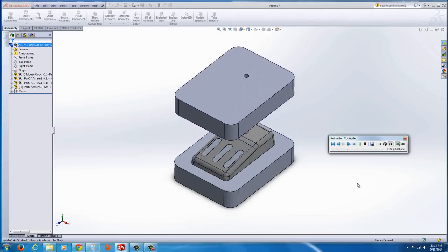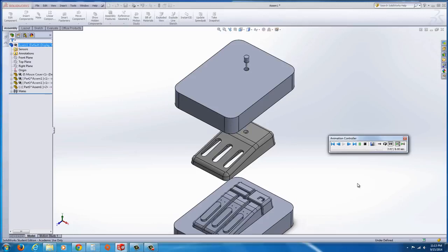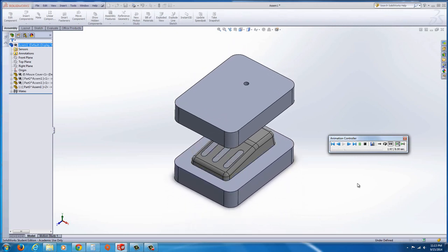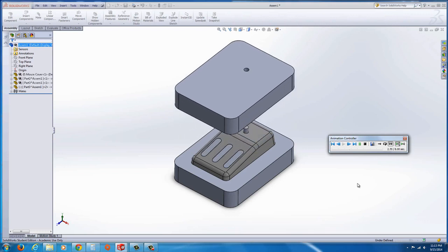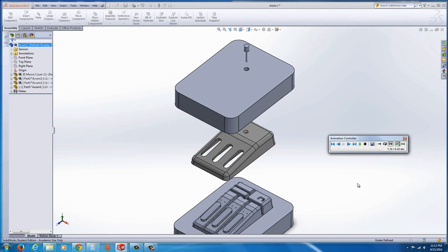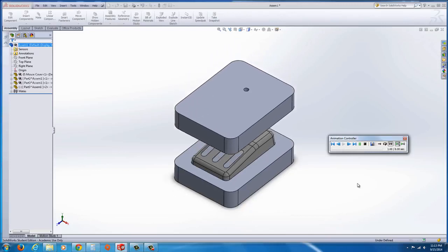In this exercise, we're going to take a look at the SolidWorks mold making tools, really in this case just the cavity, and most of it's just manual creation of a cavity and a core. And this is actually the earliest method that used to be able to use inside SolidWorks. And the thing is that it's always tried and true. Virtually always works.